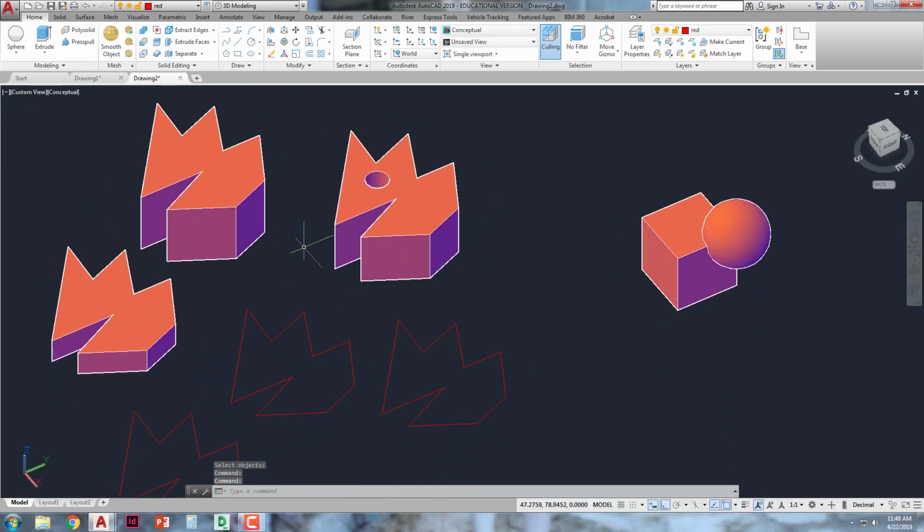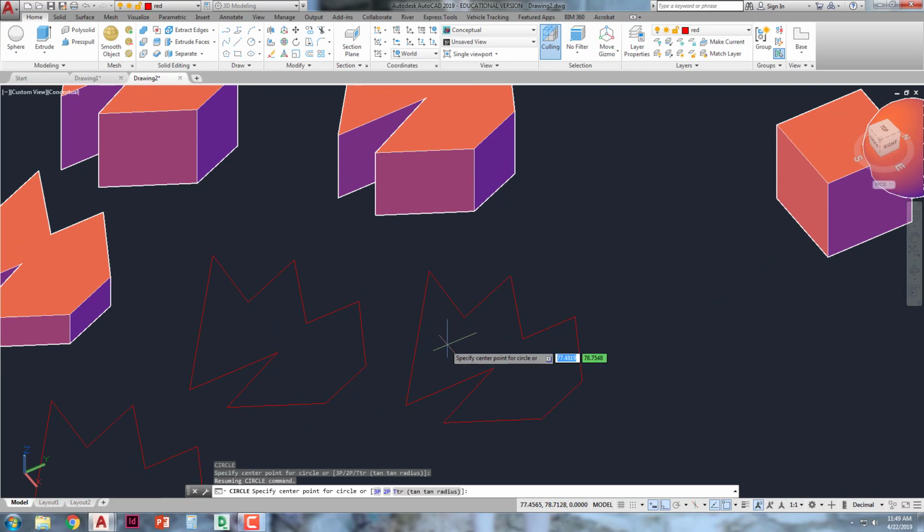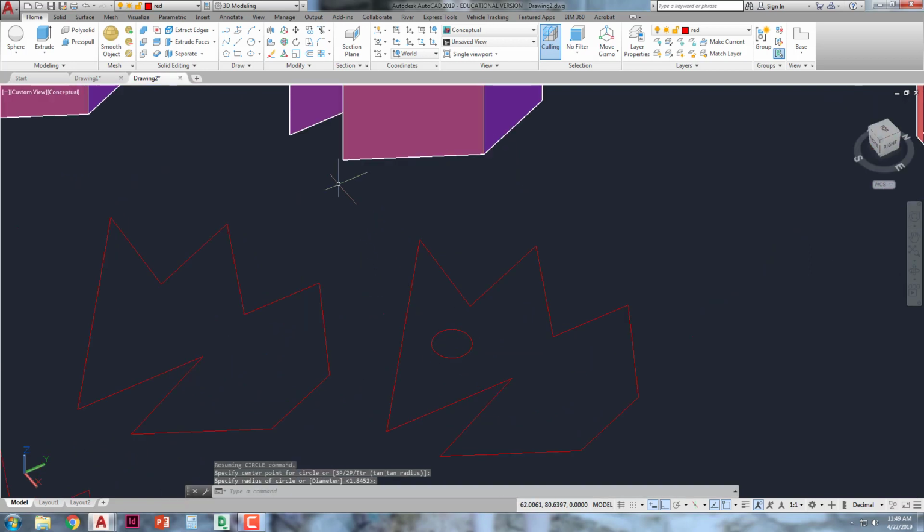Anyway, that's doing it with the extrude command. So I had to join all those lines together, extrude, and then subtract out that cylinder that extruded with it. But check this out. This is a super sweet command. Let's go draw an eye on this guy. There is this other one, and it is called press pull.